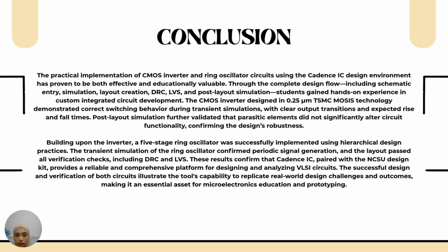Building upon the inverter, a five-stage ring oscillator was successfully implemented using hierarchical design practices. The transient simulation of the ring oscillator confirmed periodic signal generation and the layout passed all verification checks, including DRC and LVS.